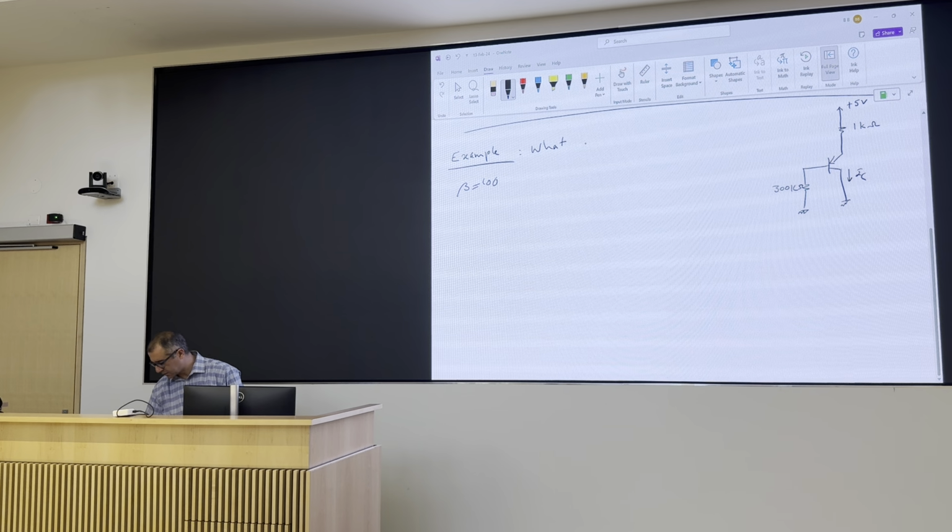And remember that for diodes, essentially you wouldn't measure anything until you hit 0.4, 0.5 volts, right? So that can happen. Your device may be in soft saturation. It still works, it's still doing its job, but you don't really have a lot of headroom. Because as soon as that voltage goes up, if this diode is forward biased by 0.2 volts, as soon as your signal at the collector is 0.3 volts, it pushes the device into deep saturation, then you're in deep trouble.